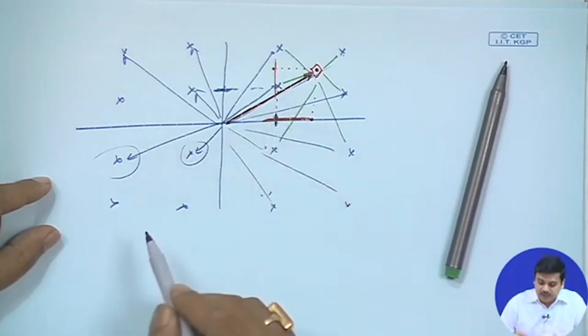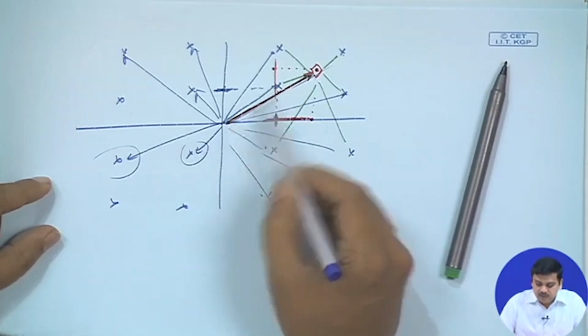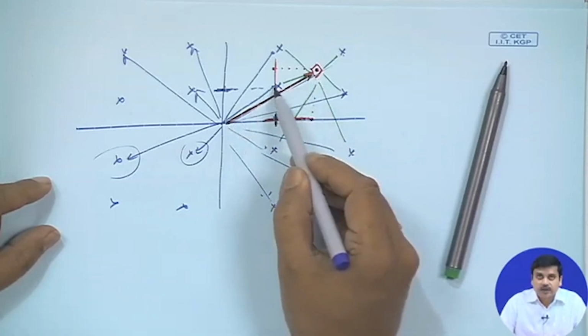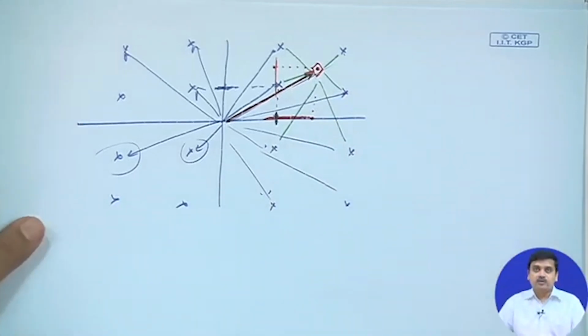So, you have to take away the bias term and take that output which is the maximum of correlation, that means the projection of this on a vector, with the bias term taken away, is one of the possible realizations. We have seen two possible realizations, but the end result is, given a particular received signal, we have to identify which particular signal was possibly sent, which is the possible waveform or the possible constellation point which could have resulted in the received signal or the received vector. So, we move on further with this.